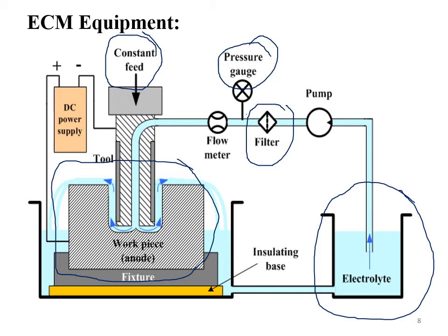The metal ions which are getting separated from the workpiece or anode will get dissolved into the electrolyte, whereas in the electrolyte solution these compounds will get further reduction and cause the emission of hydrogen gas near the tool. Finally, the further reduced compounds are taken out, like the precipitation which is going to happen at later stages. These metal ions and other things in the electrolyte are further flushed away from the machining zone.